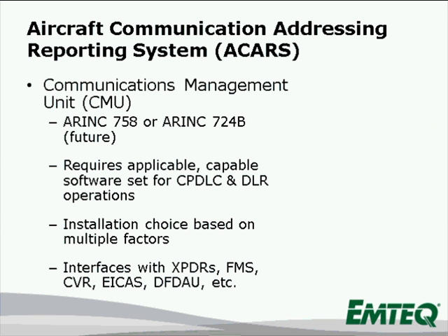Starting out with the ACARS, as I mentioned, 758 is the current requirement. In the future there may be availability to use a 724B system, but that's currently not yet approved. It does require the applicable and capable software set, so it has to have software that's specifically intended for CPDLC and datalink recording operations. That must be verified with the manufacturer when placing an order for the ACARS system, to ensure the compliant and correct software is provided.